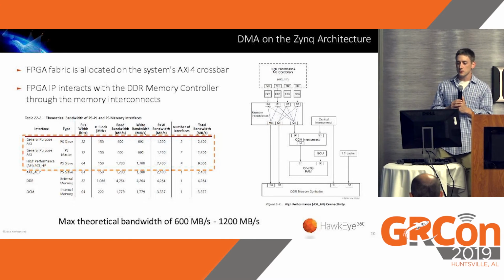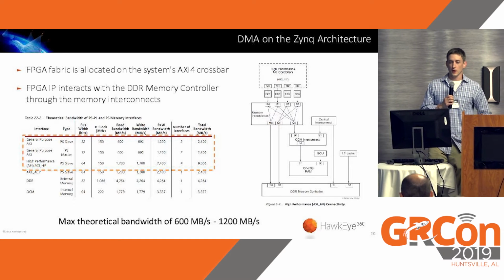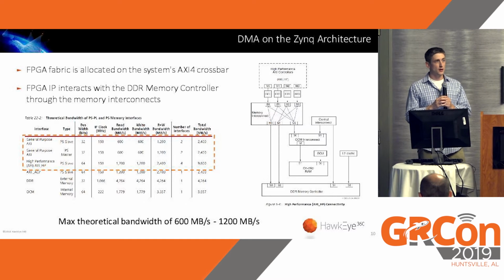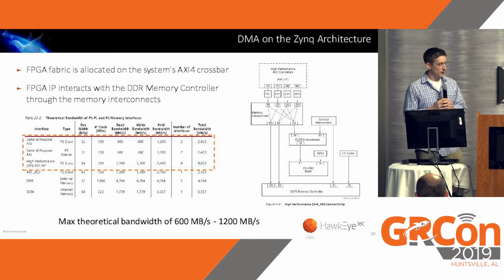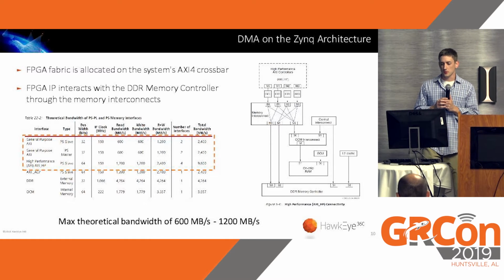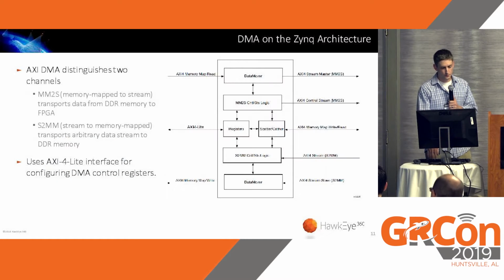So there's a lot of reasons why you won't get the full bandwidth, but ideally you could get pretty close. And 10 megasamples per second with interleaved IQ, so 4 bytes per sample, is only 40 megabytes per second, and it's not quite near the theoretical bandwidth that we're looking to be able to support.